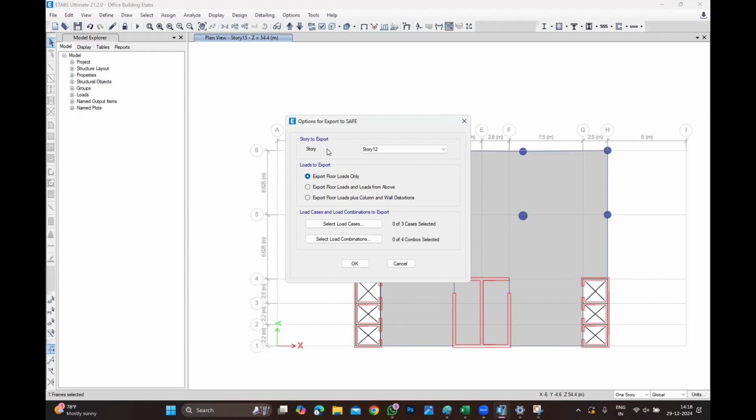Look at the columns, the moment stops here. It demands lesser reinforcement patterns. For foundation, use the third option. For slab, use the first option. There are planted columns. It's planted columns in the slabs. Still don't use the second option. Use only the first option.